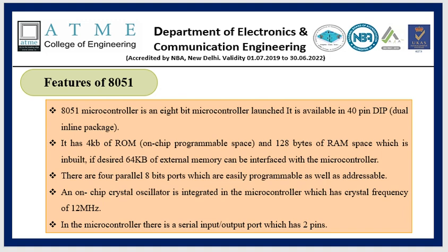The features of the 8051 are: it is an 8-bit microcontroller launched with a 40-pin DIP, where DIP stands for dual inline package. It has 4 kilobytes of ROM and 128 bytes of RAM space, which is inbuilt. If desired, 64 kilobytes of external memory can be interfaced to the microcontroller.